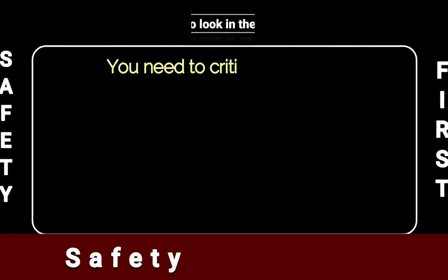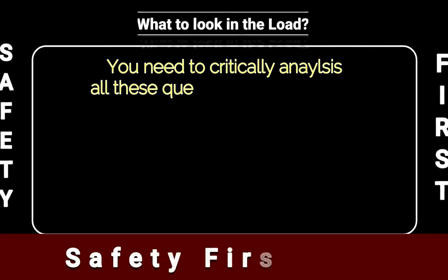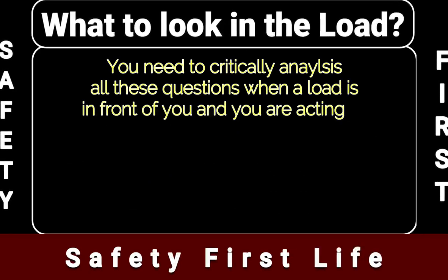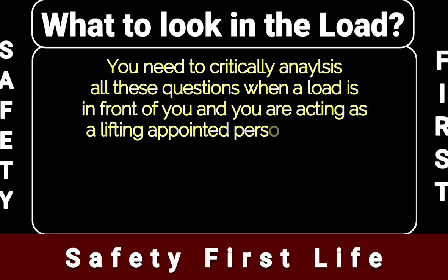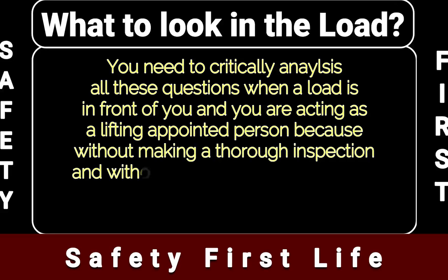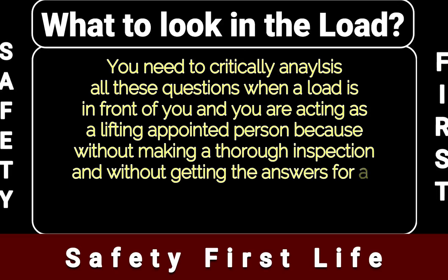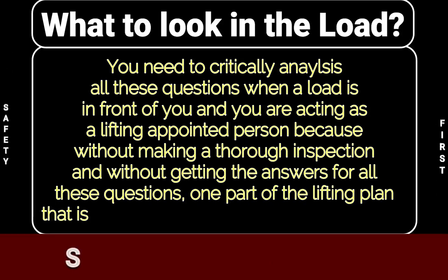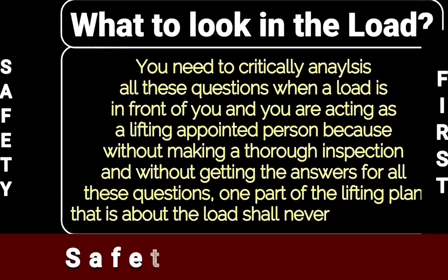You need to critically analyze all these questions when a load is in front of you and you are acting as a lifting appointed person, because without making a thorough inspection and without getting the answers to all these questions, one part of the lifting plan, that is about the load, shall never be complete.